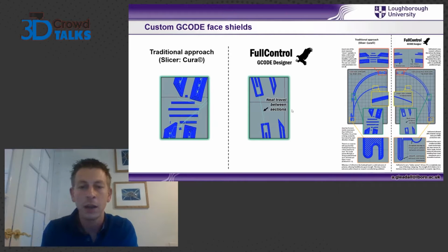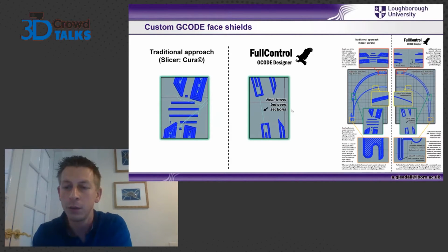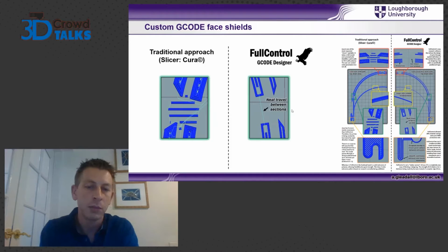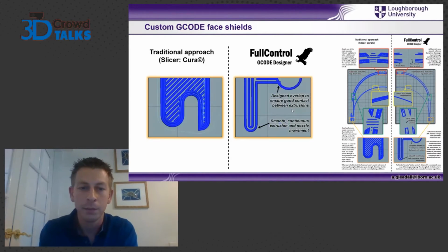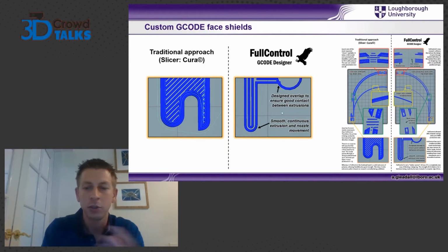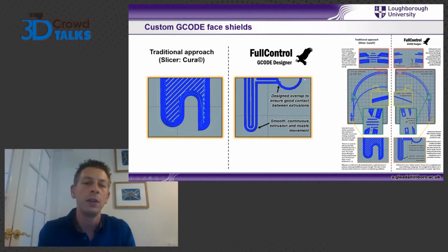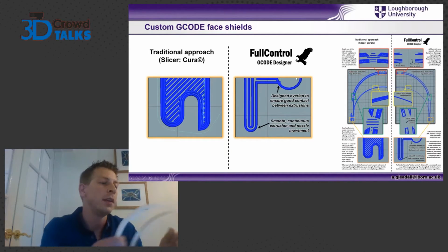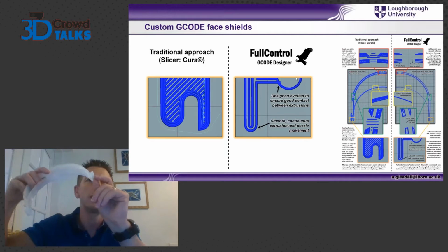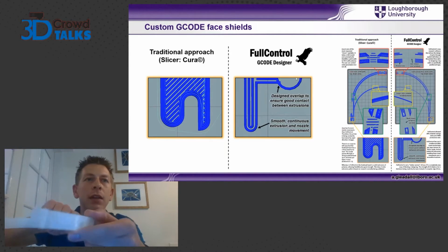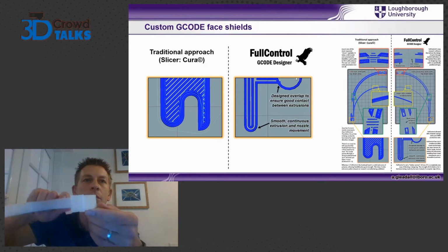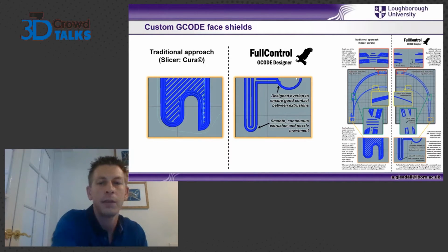This is just showing another section, and these are all color coded according to the image on the right, by the way. Another section where we've just put that travel neatly in the gap between the parts where the hole is. And that's just showing the very, very end of the structure again, getting rid of all unnecessary travel, changing the design of the loop for the hair for the elastic band. So it's now printed vertically, which means we could stack really easily because there was never any overhangs or anything. So that's it.